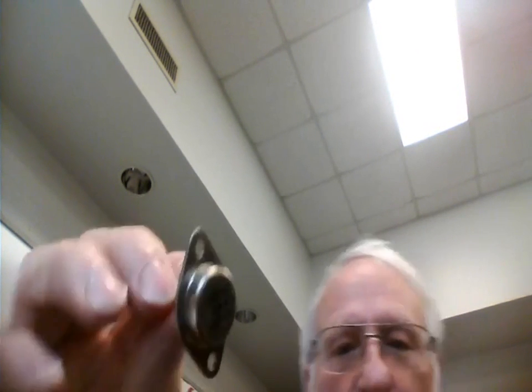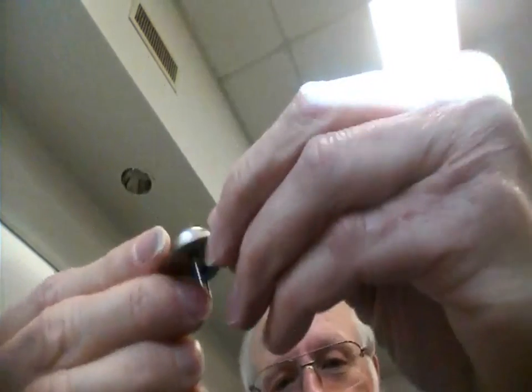I use a 3055, and it's a 115 watt transistor, if you heat sink it. So normally you'll see 3 leads, but a lot of people say, well, where's the 3rd lead? But metal's a good conductor, right? So where's the 3rd lead? It's the metal. Yeah, it's the whole metal. That's the collector right there.